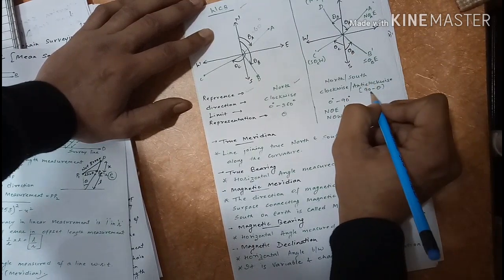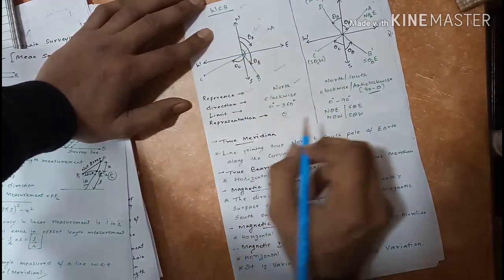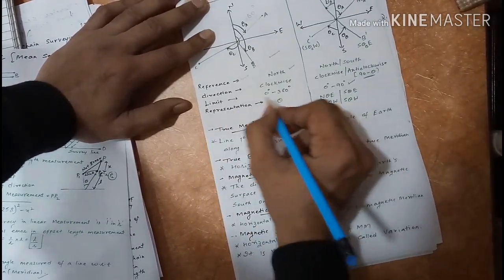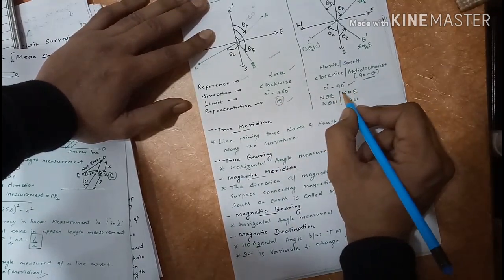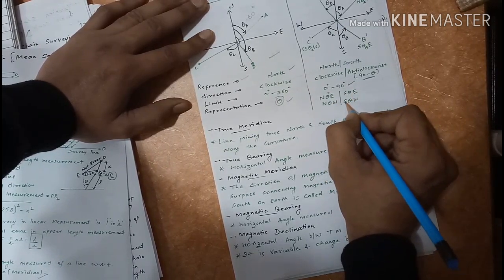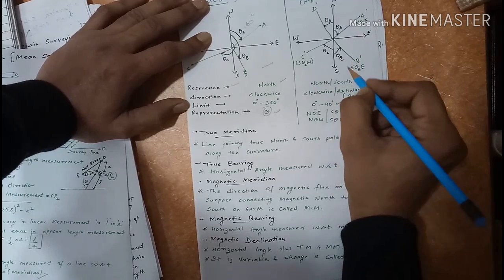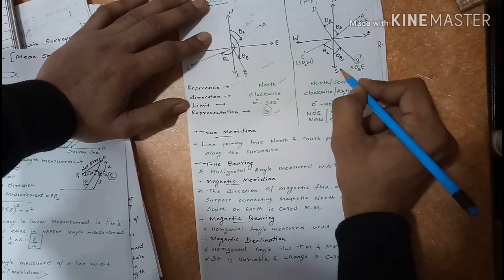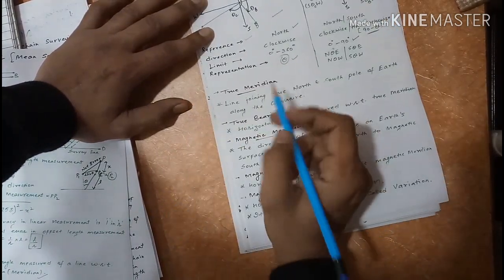In this, anti-clockwise also we can measure. In that case we have to write 90 minus theta. The limit is 0 to 360, as it is we have to represent the angle. In the quadrantal system, 0 to 90 degree is the limit. Theta is the representation, and here we represent the bearings as north theta degree east, north theta degree west, south theta degree east, south theta west, like this. For example, for this theta b, the bearing will be represented as south theta b east.